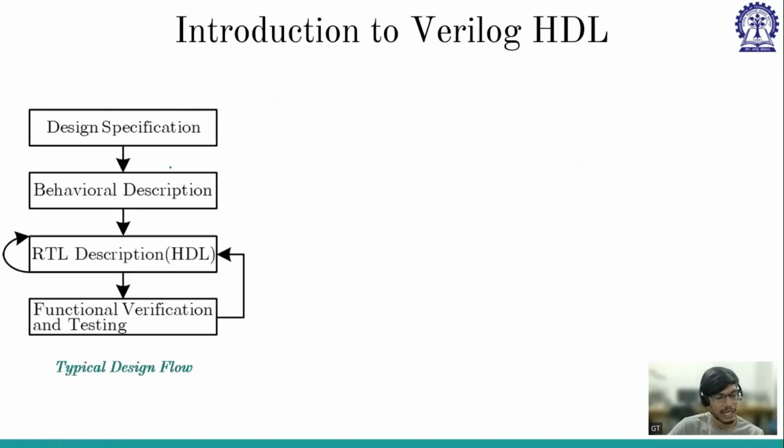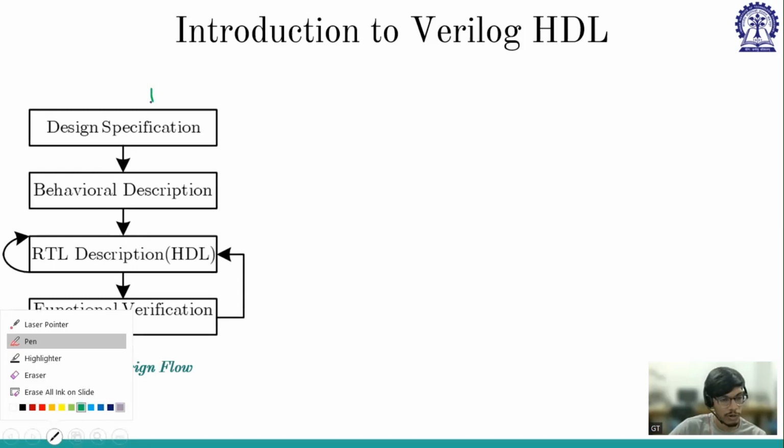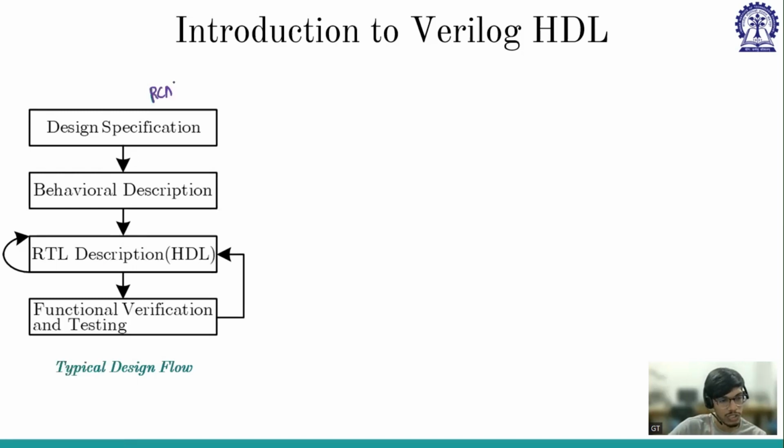The typical design flow is as follows. Say I want to write code for a ripple carry adder and implement it in the FPGA. First I have to specify my design, and then I have to describe it behaviorally. Sir has discussed that the ripple carry adder uses multiple full adders, and full adders consist of different half adders. So first I specify my design, and then I describe it behaviorally. So, to my understanding, I have fixed how I am going to write the Verilog code.